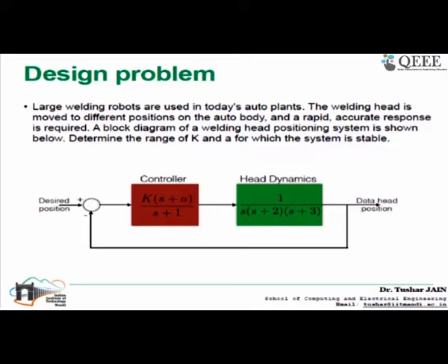So now you can imagine the situation where we have the welding robots, let's say, which are located on the top, and here they weld. Okay, there could be a batch process where they weld the different body parts. Okay, and we need to have a closed loop such that, let's say if I give the position, I have this thing, move this side, it should move in a very quick time and it should be stable, no vibration or some weird behavior to reach this path. Okay, so this is that kind of situation.